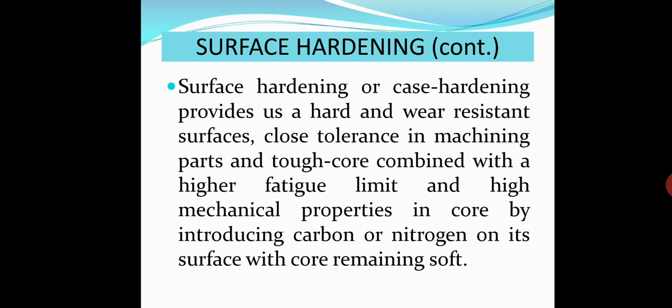This is achieved by adding carbon or nitrogen to its surface up to a certain depth, and the core remains soft. So, what is the advantage? As the core is soft, it is tough with high mechanical properties and a higher fatigue limit. And as the surface is very hard, it resists wear and tear.